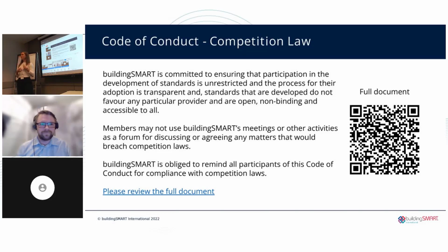The reason why we really wanted a joint session with some of the other rooms is because, while we're working on the project, we are identifying airport-specific objects. We won't be extending the schema as in adding to it, but we're going to be using the buildingSMART data dictionary to extend the schema with the airport entities, meaning that we have created a mapping to existing IFC entities based on IFC 4.3.